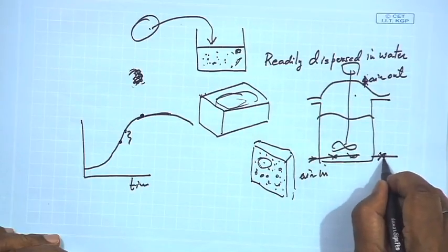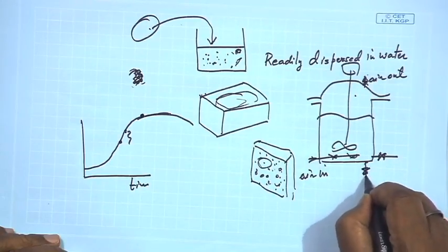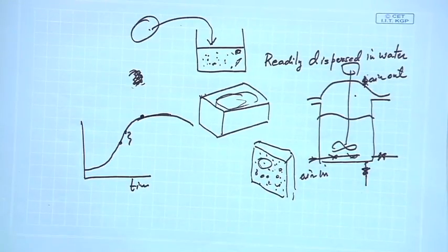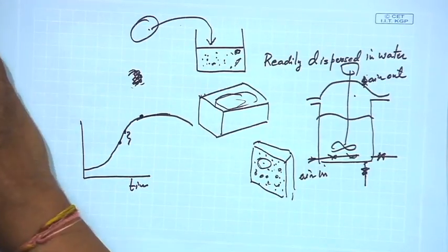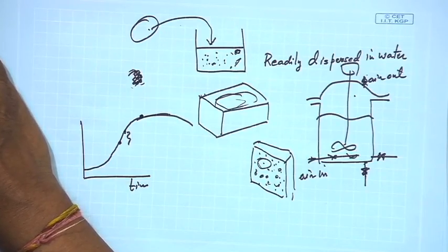Then there will be a manhole that might be at the bottom. You take the material out, that is, the media is taken through the manhole, and at the manhole we have a gate valve. I have already shown you what is a gate valve, what is a globe valve and other types of valves. This gate valve is used in the case of the manhole.